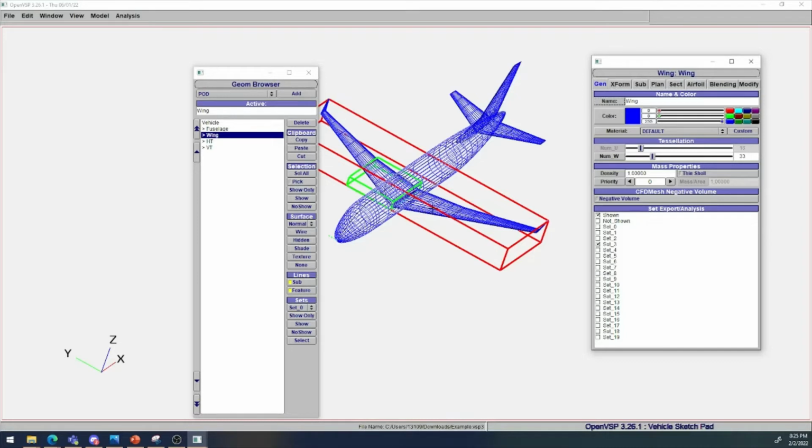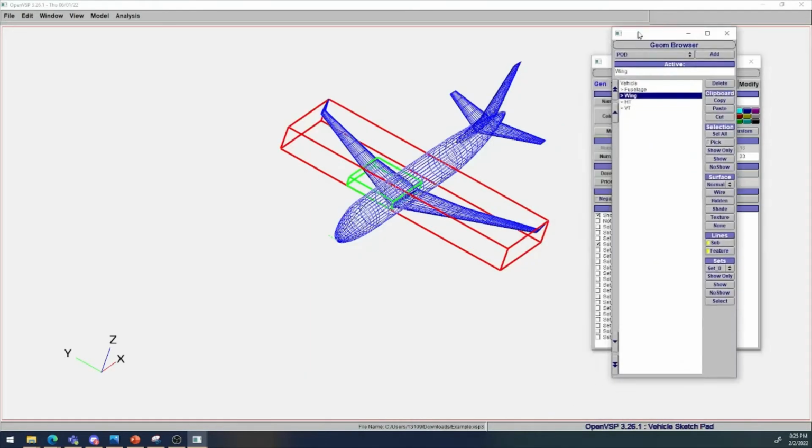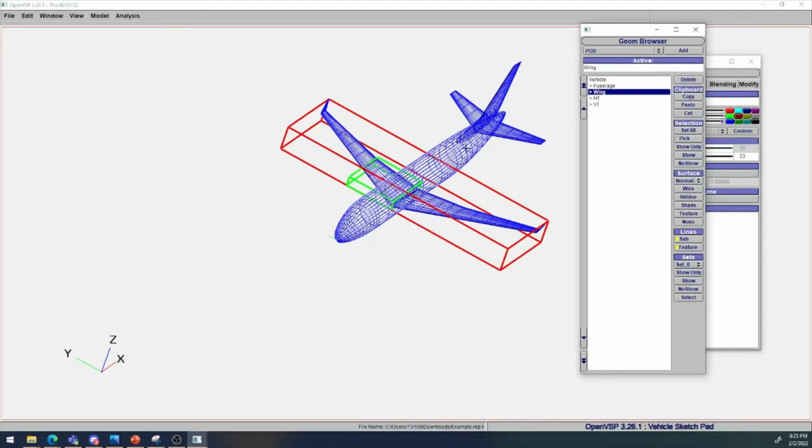So I guess when you first do modeling of this, make your mesh fine, but not too fine, because that does drive how long your computation takes. And I can go into the specifics of this. Right now, I think if you use default settings, it should be fine. And if you see any singularity points, that will be appearing in the analysis.